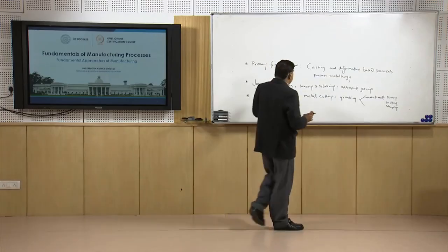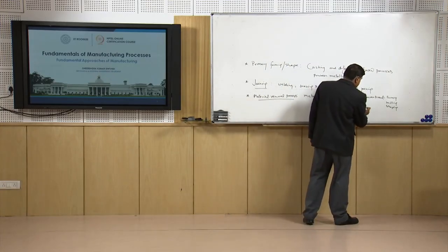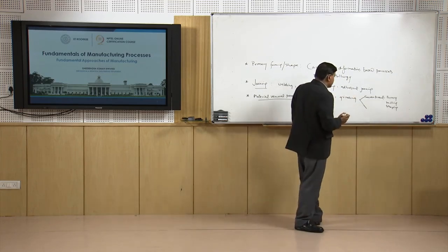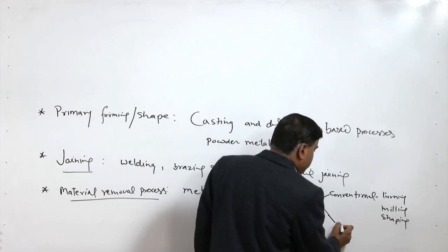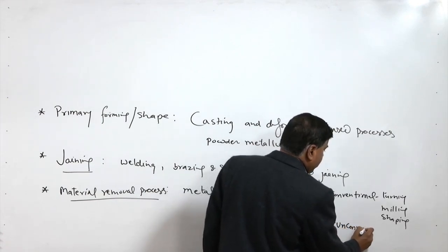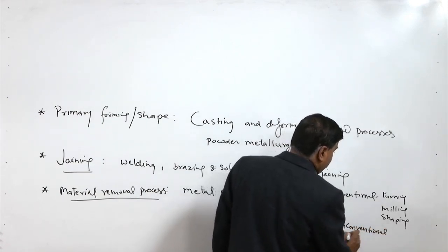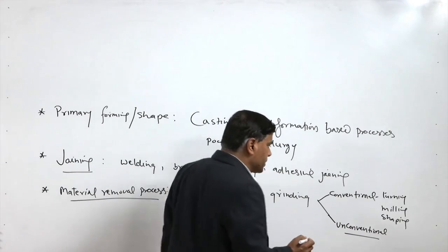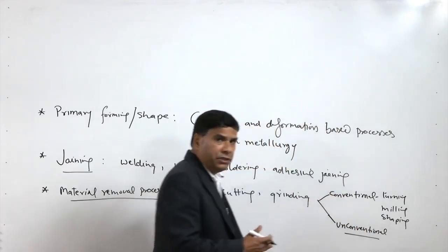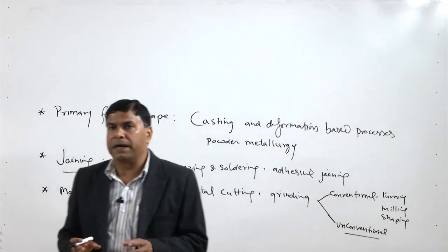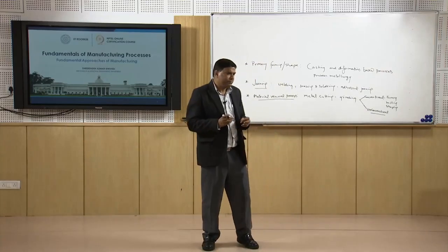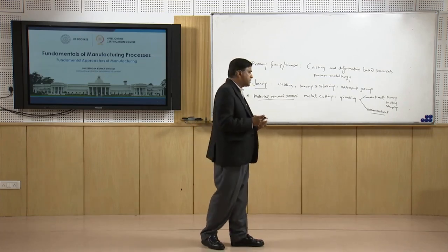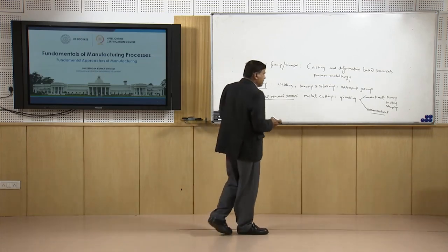But if it is about exotic materials which are difficult to machine by the conventional metal removal processes, then newer machining processes or unconventional machining processes are used, and they are based on different approaches, like use of heat, use of impacts, use of spark, or use of laser radiations, use of chemical interactions and chemical reactions.